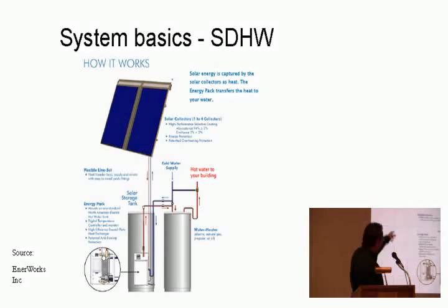So the basics of it, you have solar panels that are mounted either on a rooftop or on a ground mount type system facing south. You have piping which runs up to the solar collectors, and that contains the heat transfer fluid. And then in this particular system here, you see the rectangular box mounted on the left tank. That's actually the pumping station.